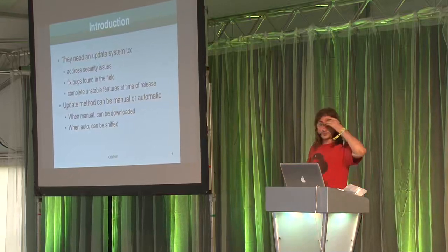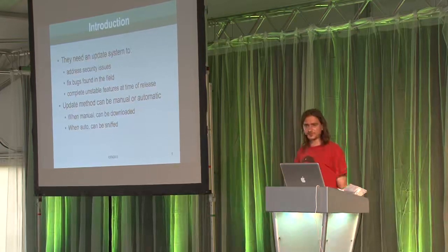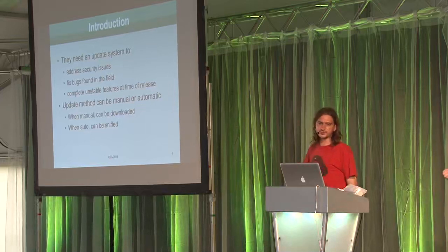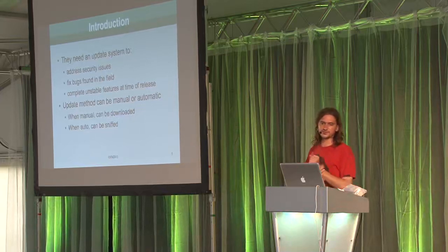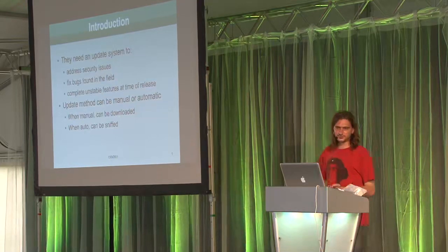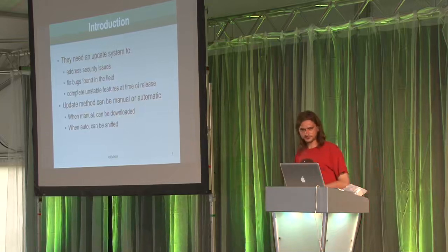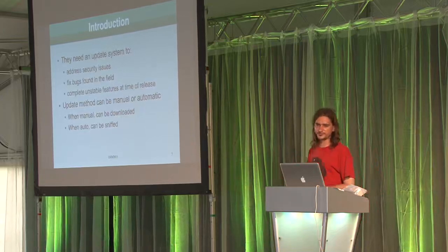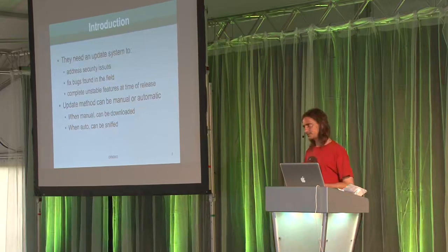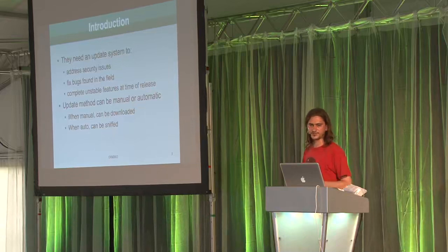So we want to take advantage of it because if you have a firmware update system, it means that you can either download the firmware when it's manual or you can sniff it when it's automatic. Because with your modem, generally when it's updated, you don't have to download the firmware update image. The operator decides for you that your modem needs to be updated, and then the downloading and flashing of your modem will be done automatically.